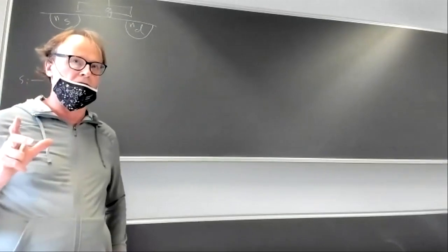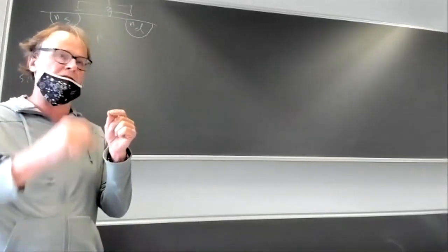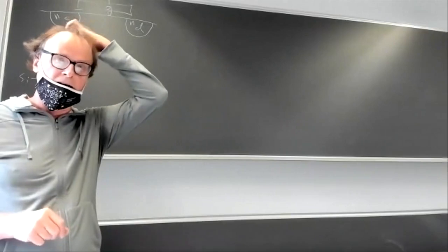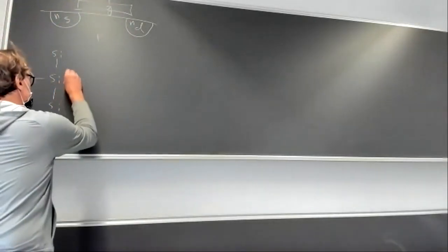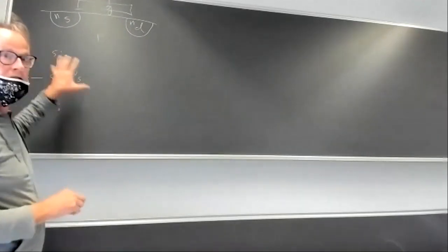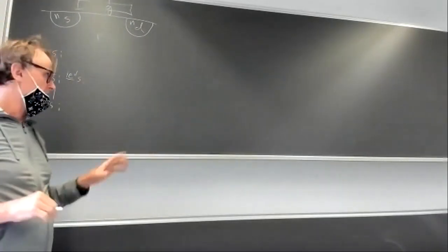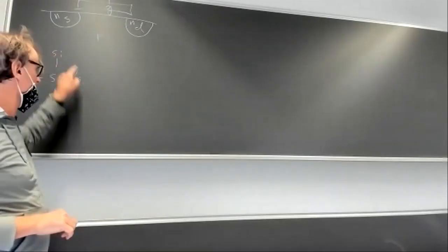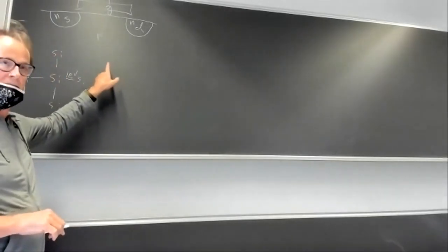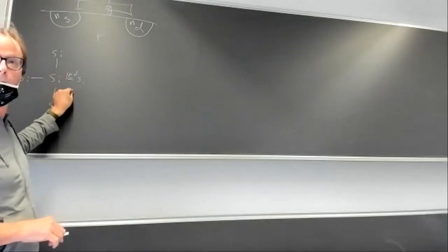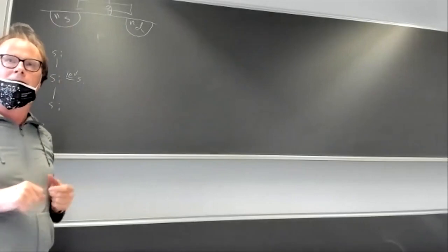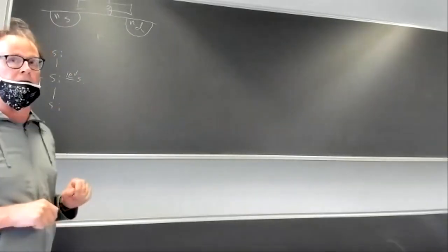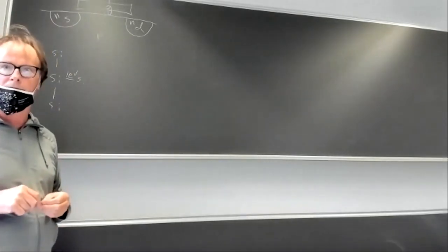And since the thermal energy is only about 1/40th of an electron volt, the average energy of vibration is about 1/40th of 1 electron volt. It's a tiny fraction of this band gap energy of 1 eV to get it loose. So that means if you just take pure silicon, then there's only a very few free electrons. And every time you get an electron off, you leave a hole behind. And both the hole and electron can move around like free particles, quantum mechanically. But if you just take pure silicon, there's very few carriers, okay?